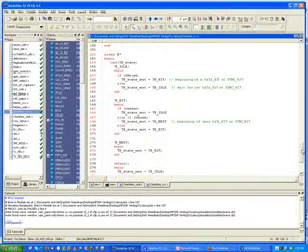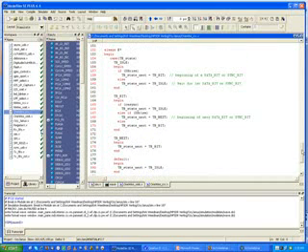Then the next always block that I have in here, you'll notice I said @ star. I could have a sensitivity list where I list everything, and that would be in accordance with the 1995 Verilog standard. This will work according to the new 2001 standard. As early as last year, though, I did see there was one case when I was using the Xilinx ISE tools, that it wouldn't take this for a particular thing that I was doing that had to do with some generate statements, which are part of the new 2001 Verilog standard.